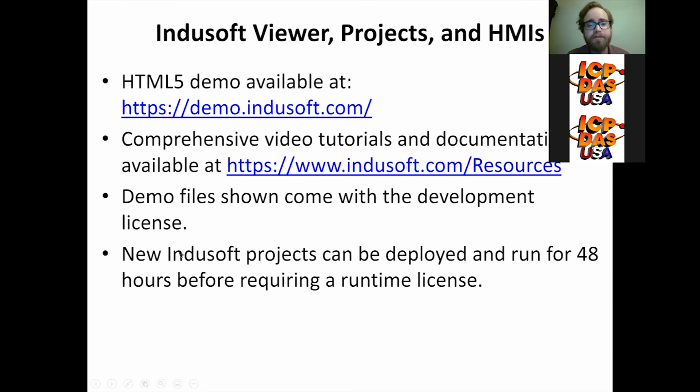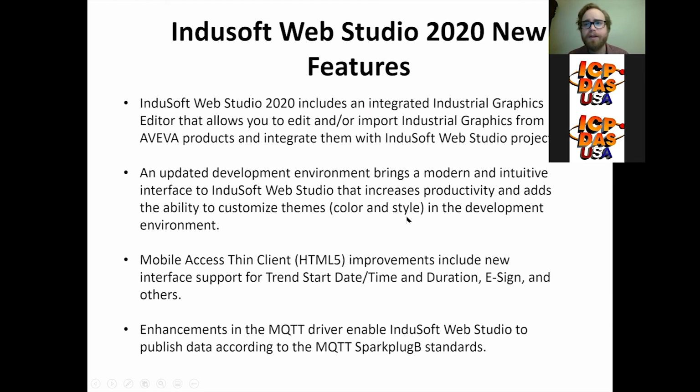Also, an interesting thing for development is that new Indusoft projects can be deployed and run for a short time before requiring you to purchase a runtime license. So if you do have the development environment, you can actually deploy and run them for about 48 hours before you need to purchase the runtime license, just to see if it's going to work the way you think it is.